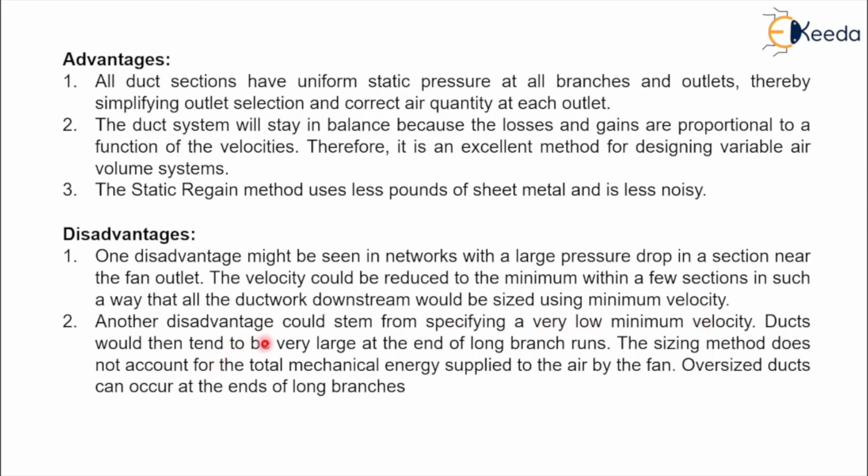Now another disadvantage could stem from specifying a very low minimum velocity. In that case, there is a high pressure loss where we are using the fan. As the air flows in the duct, at the end of the duct there is a very low velocity, and at the outlet of the fan there is a very high velocity. That's why there is a pressure loss. These are the disadvantages. Ducts would then tend to be very large at the end of a long run.